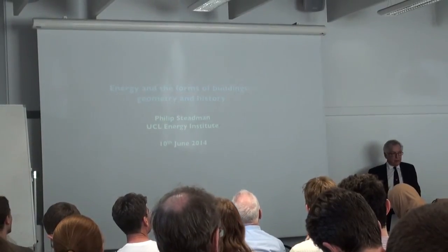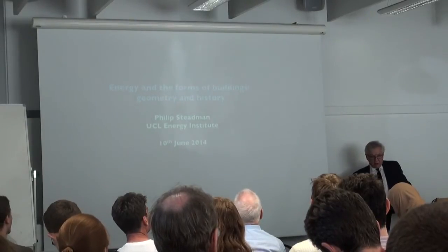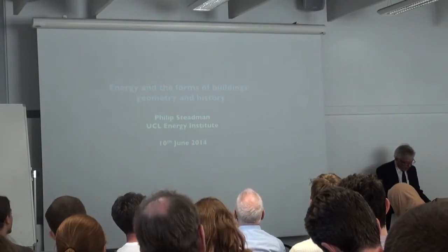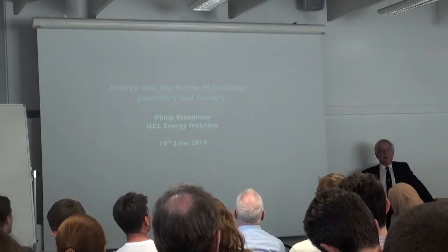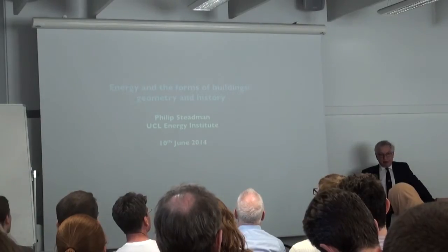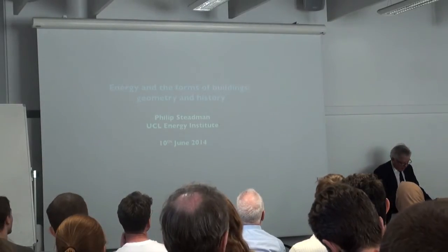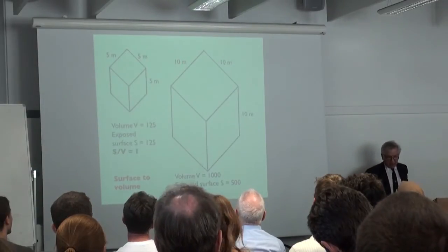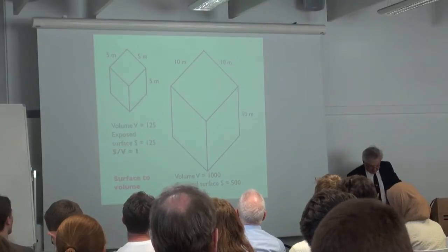And indeed, if there weren't, why should so many people spend so much time putting geometrical data into energy simulation models? I'm going to make use of three simple measures to describe the forms of buildings at an abstract or generic level so that one can generalize. And the first of my measures is the ratio of a building's surface area to its volume. Surface area S, volume V.